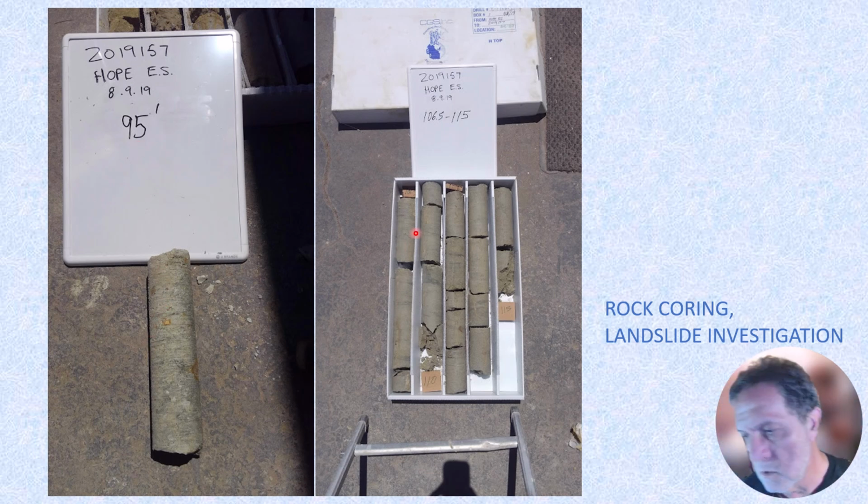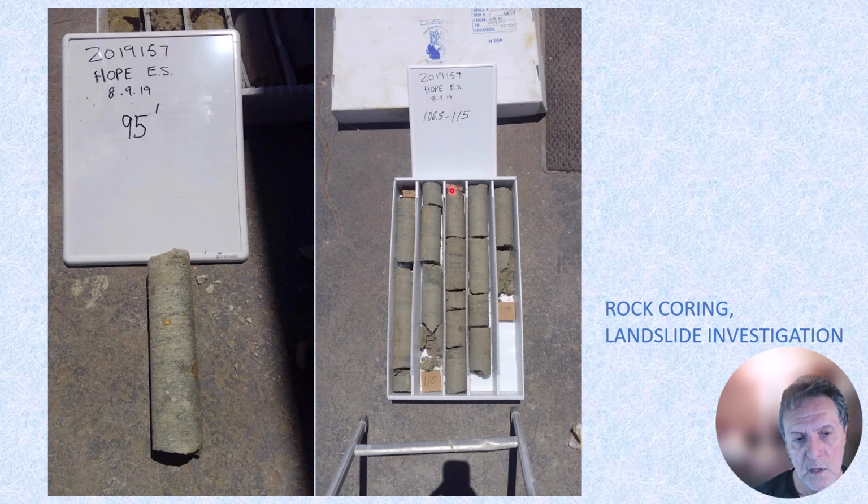In order to core rock, you need a special kind of drill rig that can core through rock. Diamond bits, using a lot of water and high-speed rotation. So this is what the core looks like when it's extracted, and it's important to keep in mind the sequence of the sampling. So this is the shallower sample, then the next deeper, and next deeper, and the next deeper, and then the deepest.